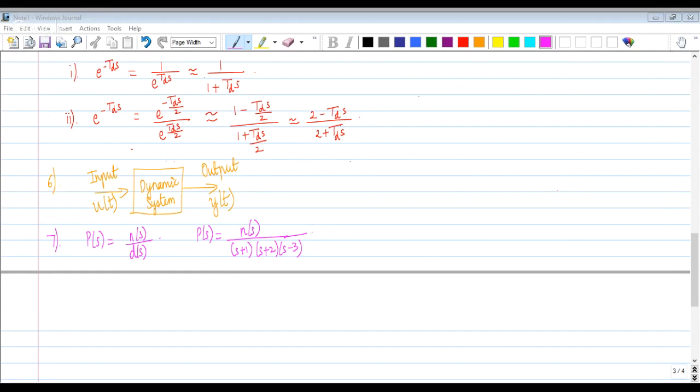On the other hand, as we just discussed a few minutes ago, if I have non-repeating poles on the imaginary axis, I'm going to have an unbounded output for a particular bounded input, right? So that's how, based on the transfer function, we can decipher it.